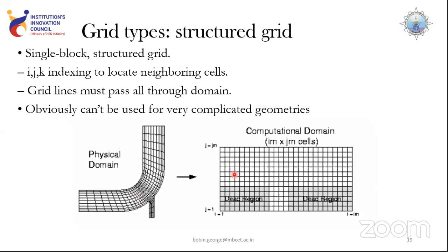If I can divide this into very fine areas like this, I can index it in three-dimensional space as i, j, k. That means I can properly identify where the cell is with respect to the domain I have. And obviously, one of the most fundamental rules in CFD is that whatever domain you have, that domain must be included in the grids, or grids must be included in the domain that you have created. You can't solve a physical phenomenon without the help of grids being generated.